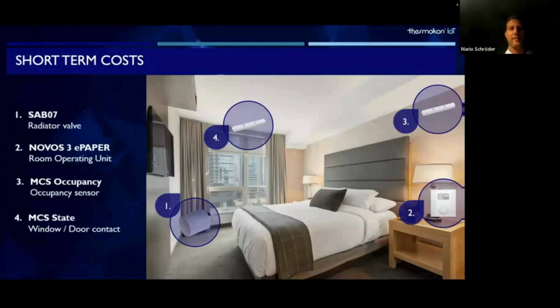And then you also have the opportunity to control state contact. Is someone in the room? Yeah, heating should start. Is nobody in the room? Heating goes down. Same functionality with the window contact. Is a window open over a longer time period? Then stop heating. So all these devices help to make the building more sustainable and more energy efficient.